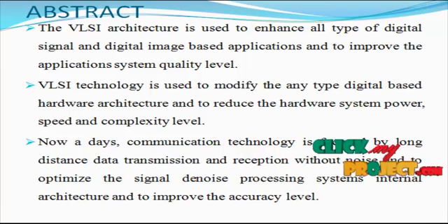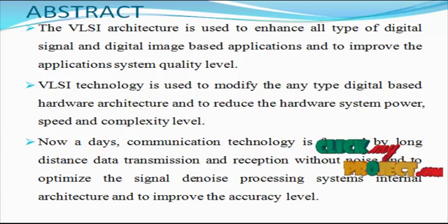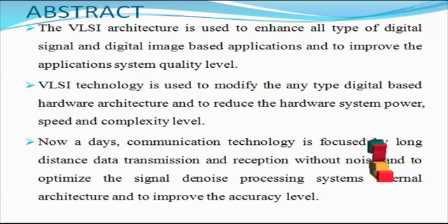The technique we developed in this paper can be summarized as follows: a simple low-pass filter and the discrete cosine transform modulation are utilized to generate the uniform 9-band filter bank first, and then all the elements of z⁻¹ are replaced to obtain a non-uniform filter bank. A recursive structure and variable length algorithm is further developed to efficiently accomplish the DCT modulation. Thus, the spectrum of the LPF can be easily spanned and the location of the desired central frequency flexibly extended.